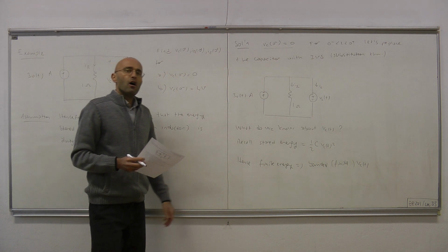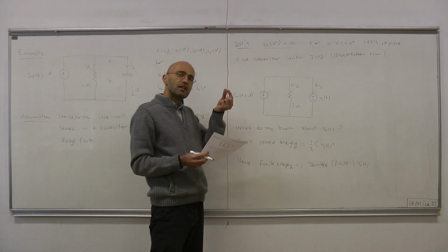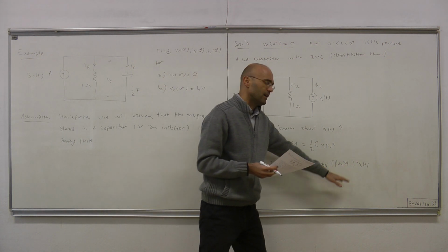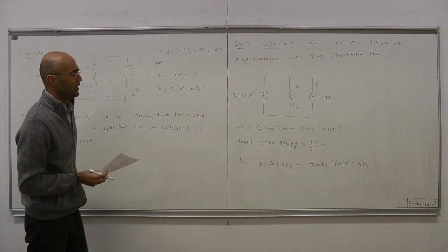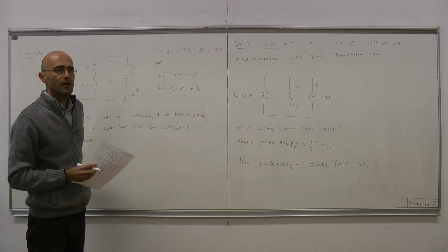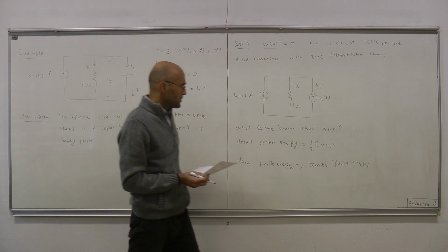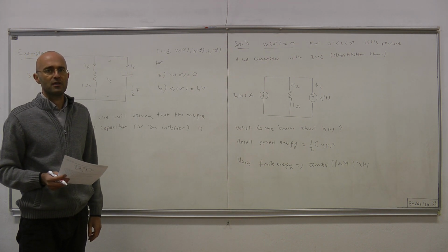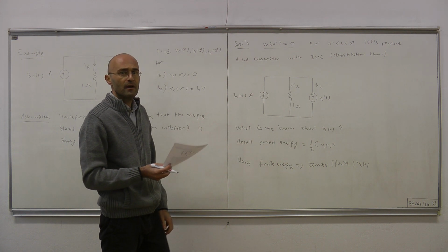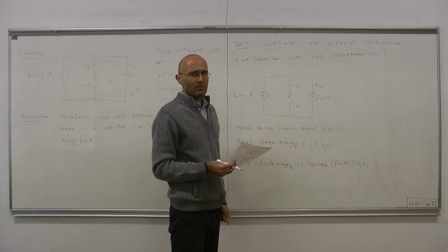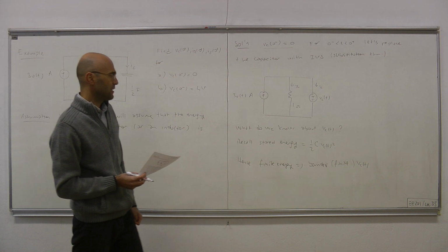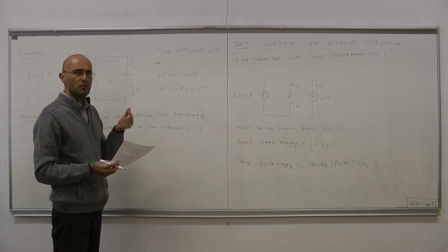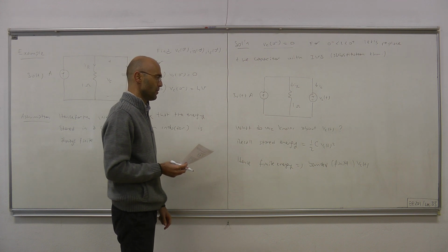So bounded means it can do all sorts of stuff in any given interval. It can reach perhaps very high values, but it will always be finite. It will not be arbitrarily large. The type of waveform that violates this boundedness would be, for instance, the behavior of the impulse function. If some voltage can be represented by some impulse function, then clearly that's not bounded in an interval that contains the point which makes the argument of that impulse 0.